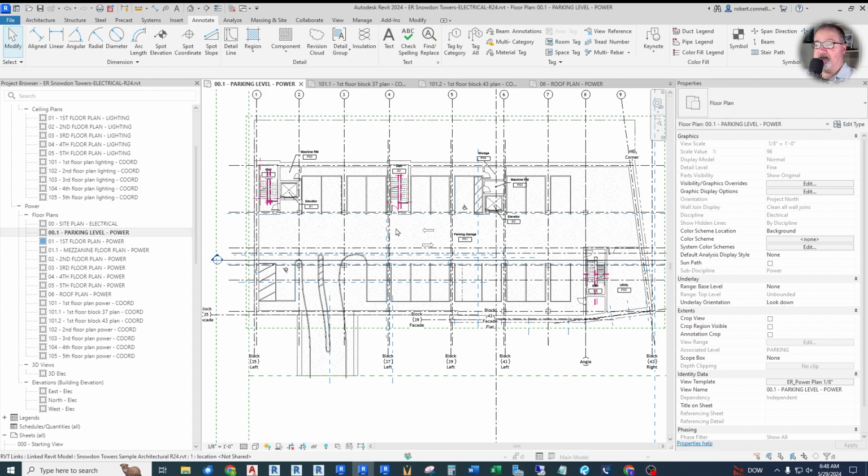And a lot of that phase is rearranging some of these loads to keep up with the rearranging walls, which always happens, but also refining that and adding some electrical distribution and starting to circuit things and add up loads, things like that. So there's kind of an order to this progression that we follow. So in this example, I'm going to break it up a little bit. I normally, again, just do a full project, and that's how I did my previous project. I did a full project with laying out all the receptacles and motor loads, and I didn't circuit till I was done. This time, I'm going to break it up because of the video format.